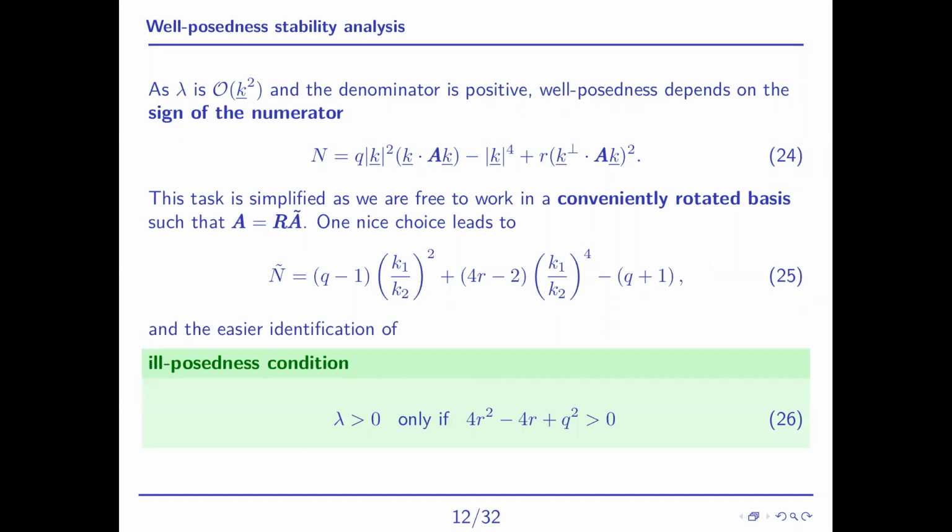And so again, we've got this strain direction tensor, as well as all the different wave vectors, and we're trying to analyze the stability of it. It can be quite complicated. We've got to consider all the possibilities, but we realize as well, because we're in this local frame, it should be rotation invariant. We should be able to choose any rotated value of this underlying strain direction, and it shouldn't affect the stability.